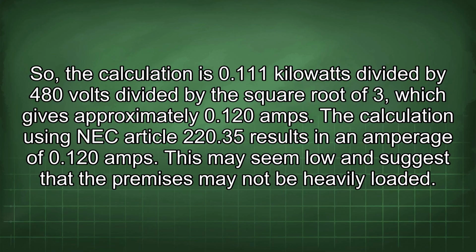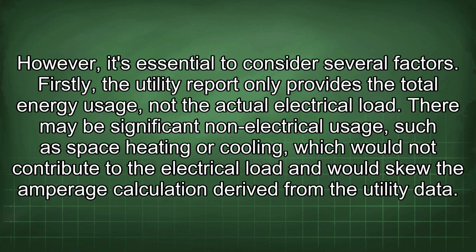This may seem low and suggest that the premises may not be heavily loaded. However, it's essential to consider several factors. Firstly, the utility report only provides the total energy usage, not the actual electrical load. There may be significant non-electrical usage such as space heating or cooling, which would not contribute to the electrical load and would skew the amperage calculation derived from the utility data.